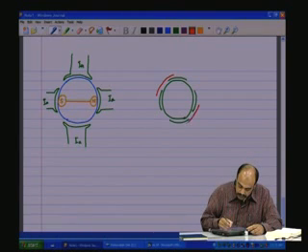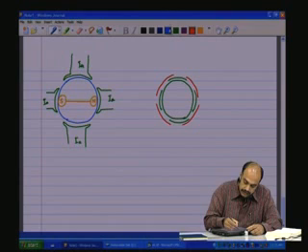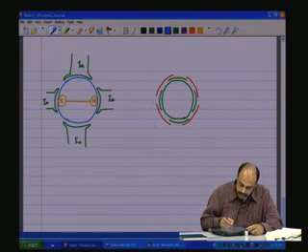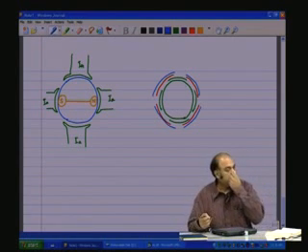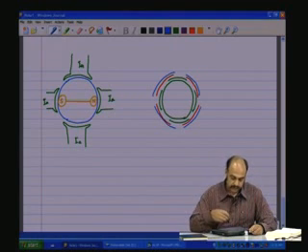You have one here, like that, and like that, and the C pole set is again shifted 120 degrees, will be in this manner. Only it is minus 120 degrees. The winding sense is changed from clockwise to anti-clockwise to obtain the 3 phases.